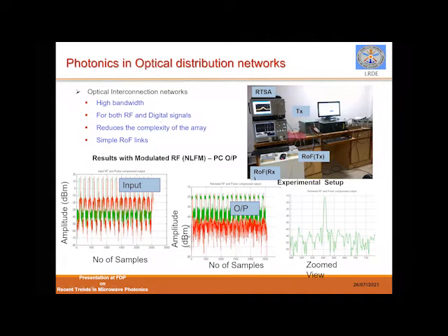So what I wanted to tell over here is, in a radar which has more than thousands of elements, there are multiple cables. Conventionally, it was carried with the help of multiple coaxial cables because of interference issues. And you can imagine that I cannot leave one cable just like that. There will be interference, so we should also properly shield it. And each shielded cable is going to add to the weight as well as the complexity of this distribution system.